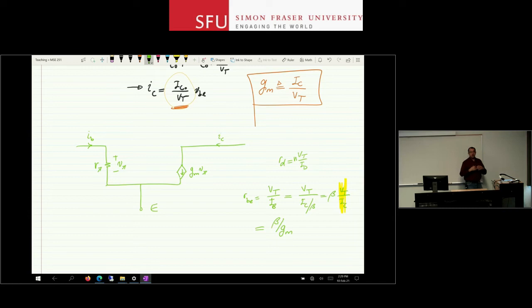So I go back to the linear domain. I do all my analysis with the linear circuit. Yeah, I may have a few, let's say, equations, KVL and KCL here and there to solve, but everything is linear. Everything is back to what I used to. And as long as my variations of base emitter voltages or currents are not too large, I should be okay.